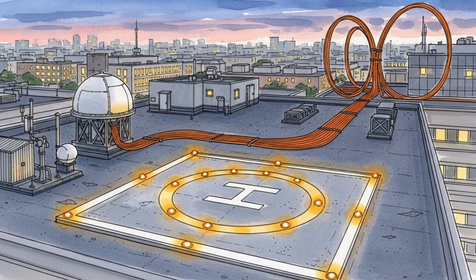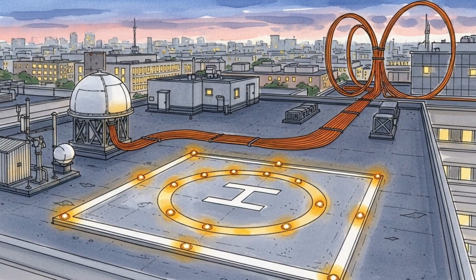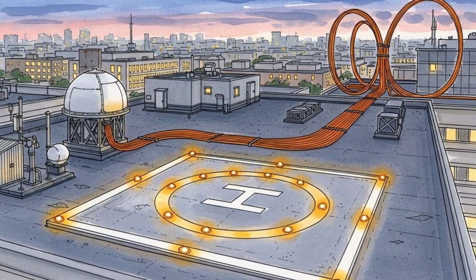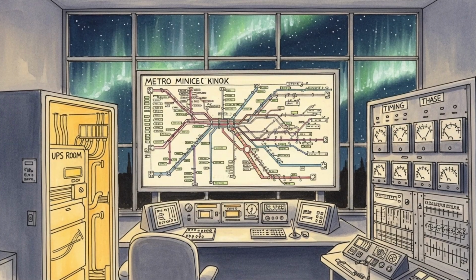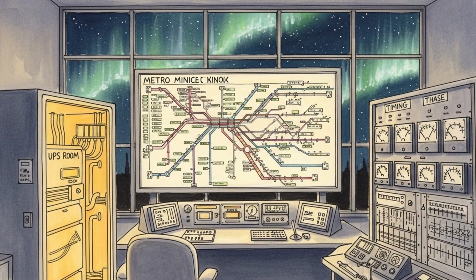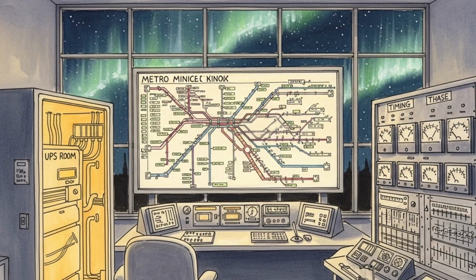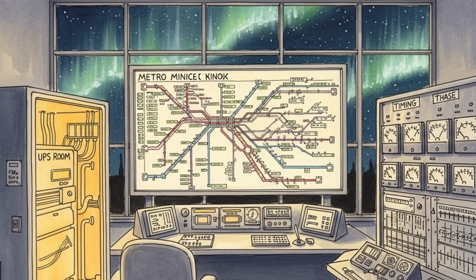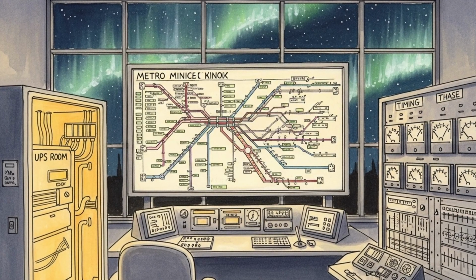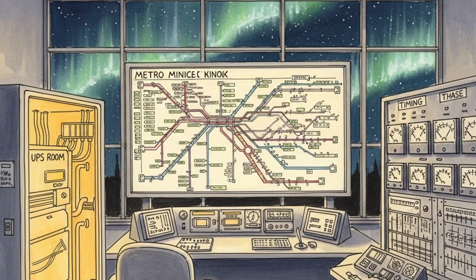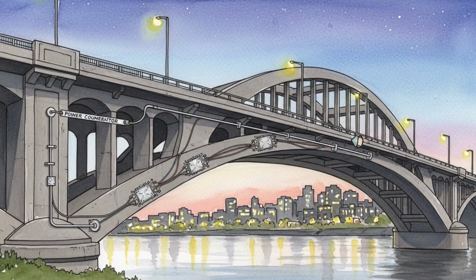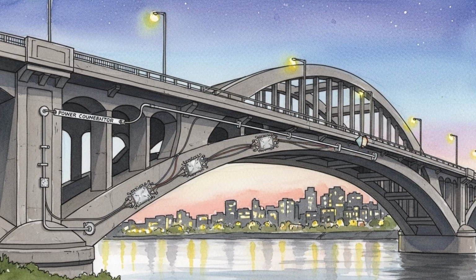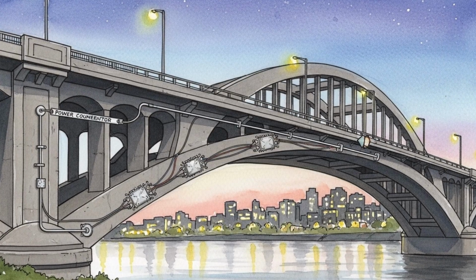Backbone networks on land are robust to induction for the optical payload, but still use long-grounded conductors for power and protection. Station earthing and bonding must remain within specification. Surge protective devices and isolation transformers reduce the path for quasi-direct currents into sensitive electronics. During storms, network operators increase monitoring of station ground potential rise, rectifier loading, and alarm rates. They postpone planned work that would place sites on single feeds or disable redundancy.